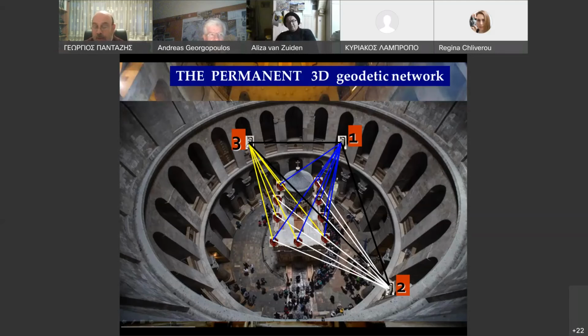The software allows the communication with the total station, the organization of the monitoring scenario, the registration of the total station's measurements to all the selected points, the check of the measurements in the data management, the presentation of the results of the check points displacement in real time, either in table form or in diagram form, and of course decision making.